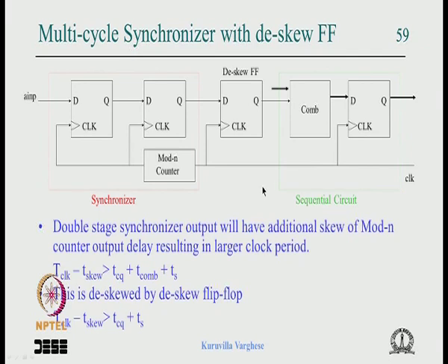So I think we are coming to the end of the lecture. What we have looked at is the problem of metastability in a flip flop that stems from an issue in the cross coupled latch used in the edge triggered flip flop. We have to meet setup and hold time, and I explained in some detail that it comes from the master latch, the setup time with some clock path inverter delay. You have to subtract it, then that delay of the clock path will add to the hold time, then the slave latch delay is the propagation delay, and we say that for successful operation it has to be met.